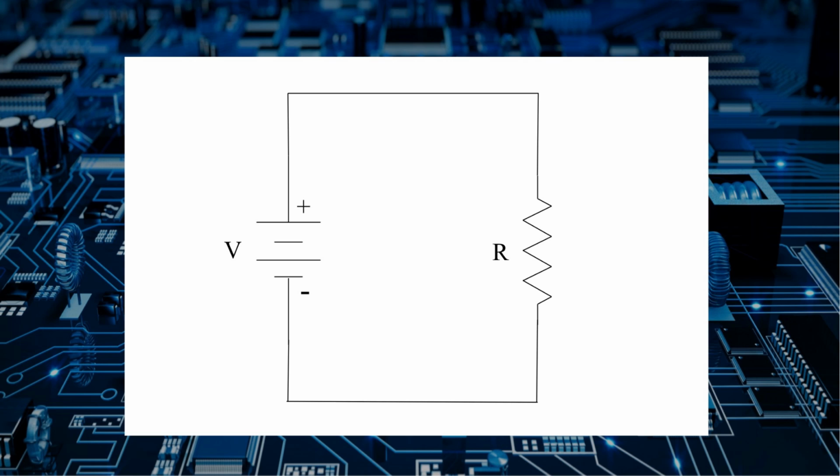The symbol on the left of the schematic diagram is the standard symbol for a battery. The V indicates voltage. A battery symbol, like the battery itself, has positive and negative terminals indicated by plus and minus signs. The long and short horizontal lines indicate battery cells. The longer line is also used to indicate the positive terminal, while the shorter line indicates the negative terminal. The battery symbol can also be drawn vertically or horizontally. The lines between the components represent wires or electrical connections, and are usually drawn horizontally or vertically with right angles.